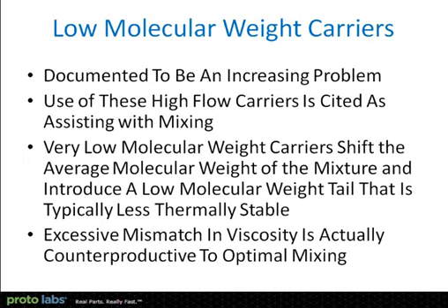The low molecular weight carriers. This is being done ostensibly in order to improve mixing. Now, it is true that matching viscosities of your colorant and your base resin is important in order to optimize mixing. You don't necessarily want to have them be the same, but if you get them too far apart, it actually is counterproductive. And so I see a lot of strategies for concentrate use that just simply do not make a lot of sense, and I'll show you an example of that in just a minute.